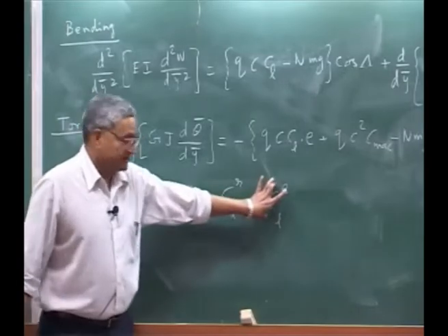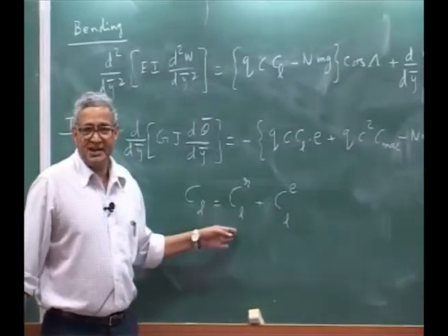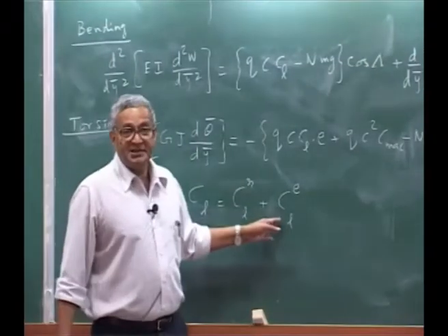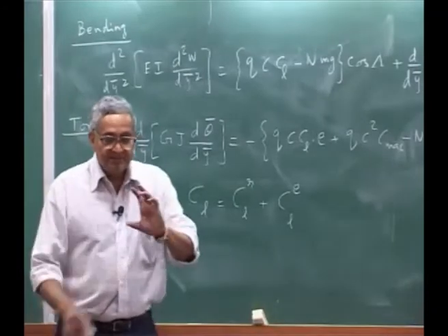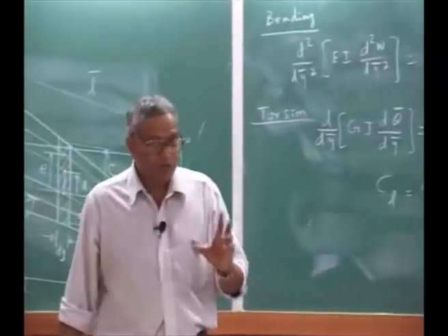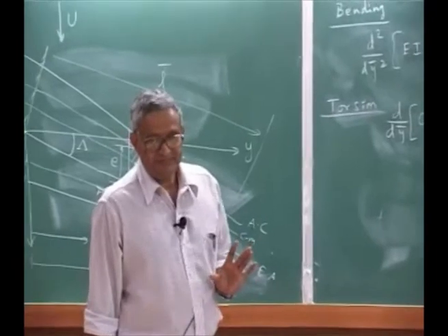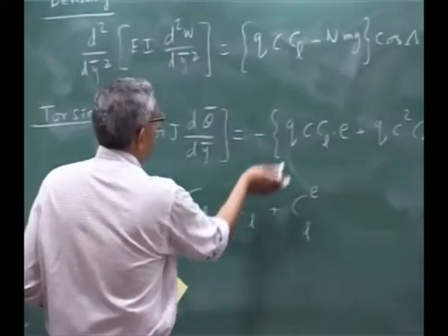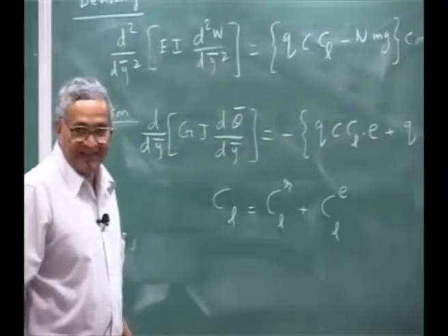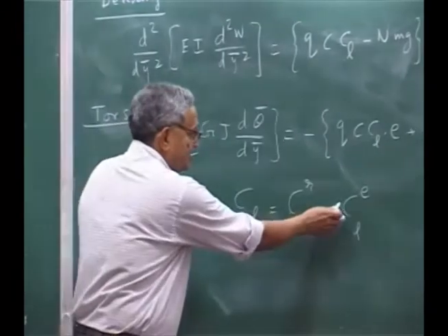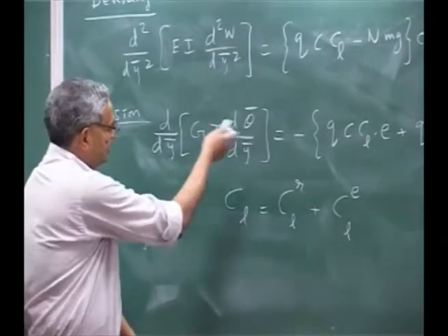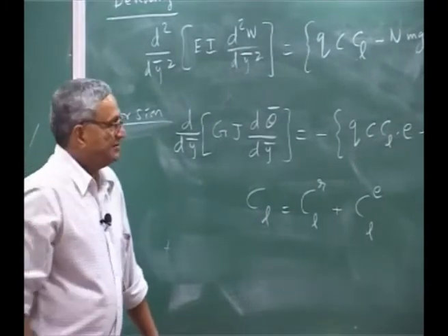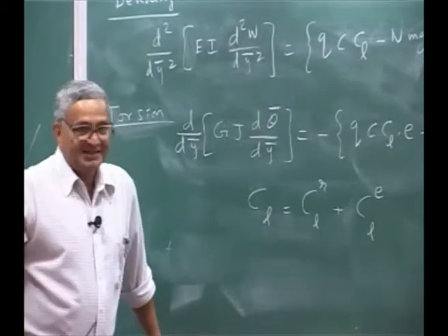I still do not know what this is. Rigid is, you can say CL alpha into alpha rigid. But here I have to know what is the deformation, the change in angle of attack due to deformation. Okay. Now if I write this, you go ahead, substitute here in every place, collect the CLE terms and put it to the left hand side. Alright. And then write the rest of the terms on the right hand side.